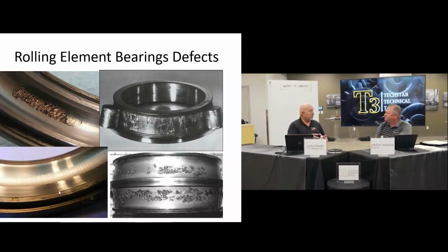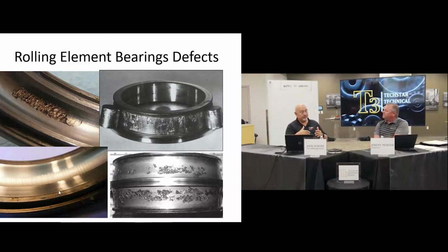You do want to know what your machine's doing, and plus what this does too is it keeps your bearings lubricated from false brinelling. Reminds me of, you leave a vehicle parked on concrete for any extended period of time, you'll get flat spots on your tires. That sounds similar. That's right. The false brinelling starts out mainly like a chuck hole in a highway, and then once you start that machine up, it shifts it away. Yeah, it's just like tires going over a chuck hole. Yeah, makes sense.